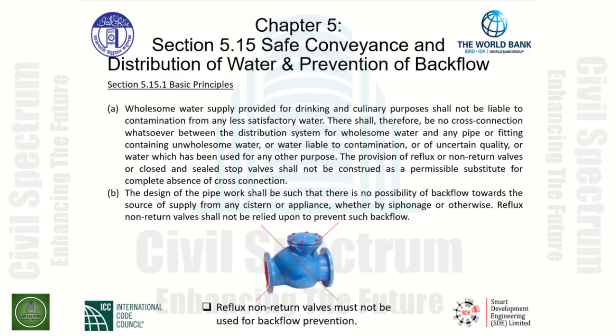containing unwholesome water. In other words, no cross-connections are permitted, or water liable to contamination, or of uncertain quality, or water which has been used for any other purpose. The provision of reflux or non-return valves or closed and sealed stop valve shall not be construed as a permissible substitute for complete absence of cross connection.